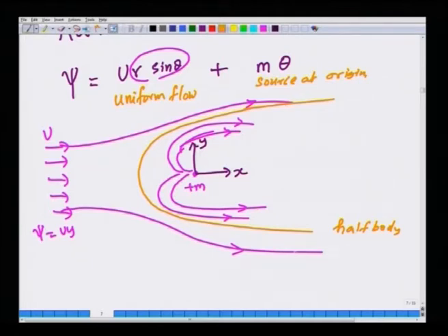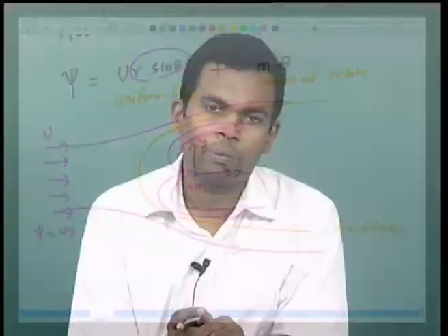There is fluid flow past that solid surface. What is important to understand is that whenever you have potential flow and there is a streamline, the streamline can be treated as a solid body, because within the realm of potential flow we can satisfy only the normal velocity condition, and there is no flow across the streamline. There is no way we can satisfy the tangential velocity condition within potential flow.